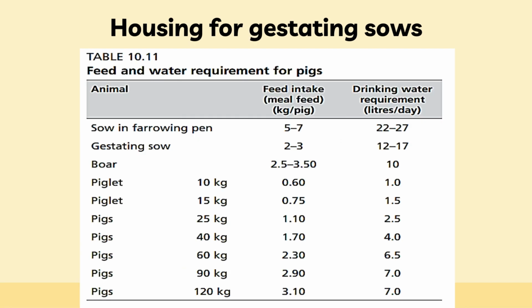Concrete troughs, often prefabricated with metal molds, are commonly placed in the pen's front wall for easier feeding, as shown in Figures 10.35d-f. Though more challenging to construct than interior placement, it's preferred. An open front enhances ventilation but is costlier due to needing galvanized steel pipes. A sloping front deters pigs from stepping into the trough, but is costlier.